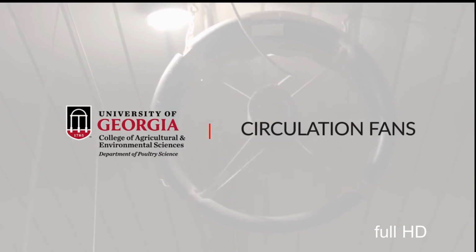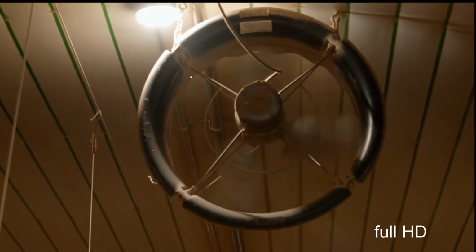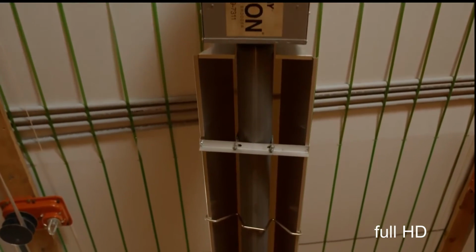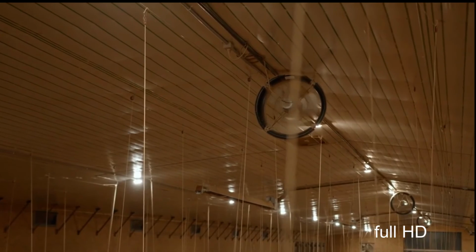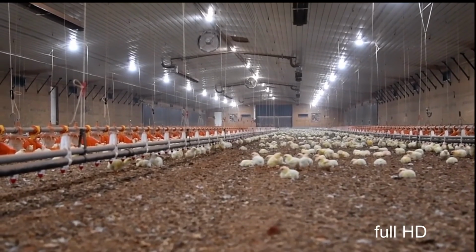Another important component of our cold weather environmental control system are circulation fans. Circulation fans provide supplemental mixing of the air in the house. Why do we need mixing? Well, first, during brooding, especially during cold weather, the hot air produced by our heaters, a lot of it ends up next to the ceiling. The circulation fans help to move that hot air off the ceiling where we don't need it, down to the birds where we do need it.